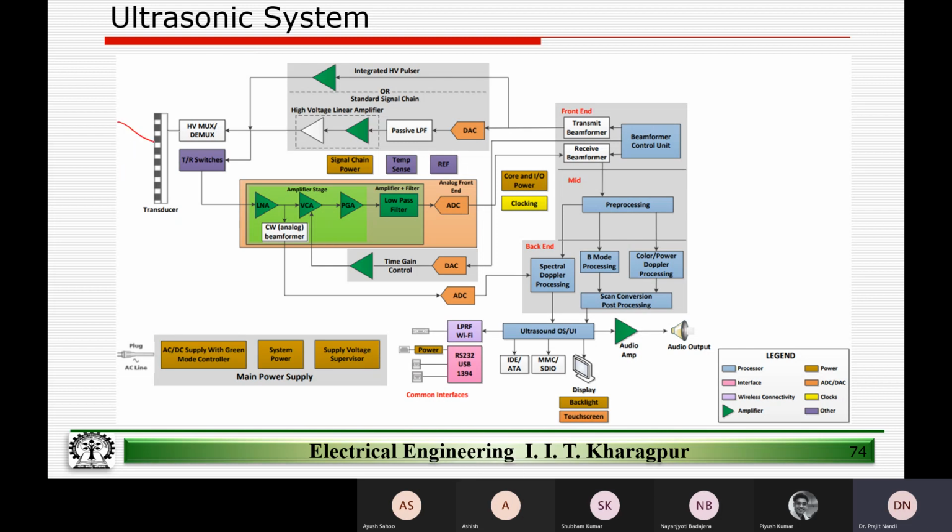And when the sound waves are incident on this crystal, we can use it as a receiver, right? Whatever we receive can be amplified. It will go through a certain electronic signal chain, and we can read the signal that we are receiving, right? So for the transmitter, we need voltage pulses.